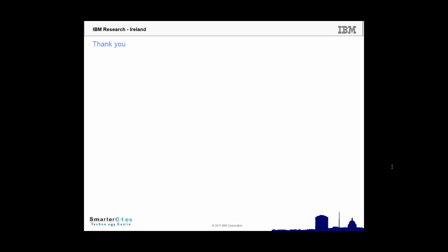So SCATS is actually able to report degrees of saturation that go probably all the way up to 1.3, or 130% or so, maybe even slightly more. It will depend on what you calibrate as the point where you have 100% occupation of your detector, and that is something that can be calibrated within SCATS. So I hope that clarifies a little bit of how this degree of saturation is calculated and why the values are higher than 100%. Yeah, thank you very much for your explanation.